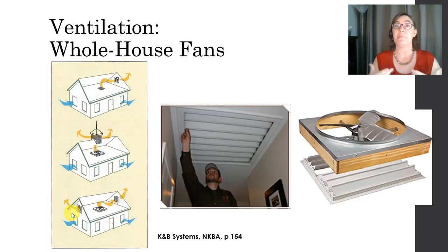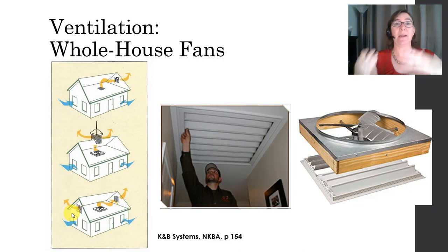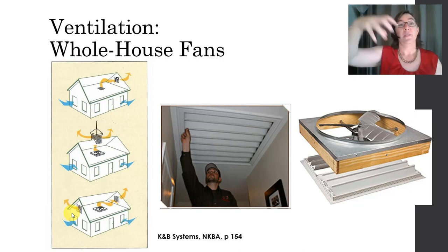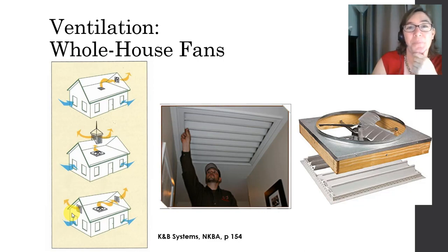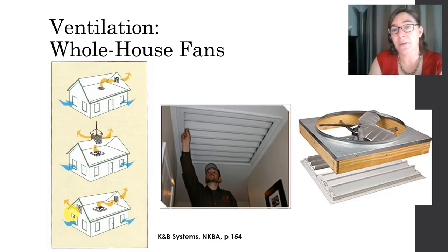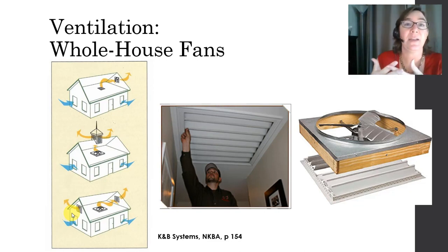A whole house fan is a mechanical system, in that, again, we spend energy to move our fan, but it is a low energy system and very, very effective. It will draw the hot air and exhaust it out of your house, and you'll want to also design for the cooler air to be allowed into your home. So if you're ever in a house and you see this type of register or grill on a ceiling, that's what you're looking at. It's a whole house fan.